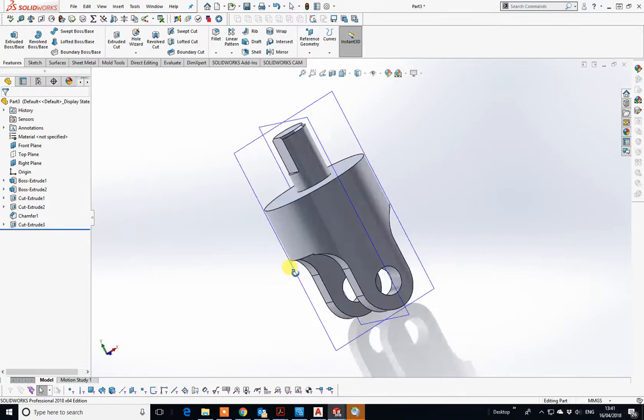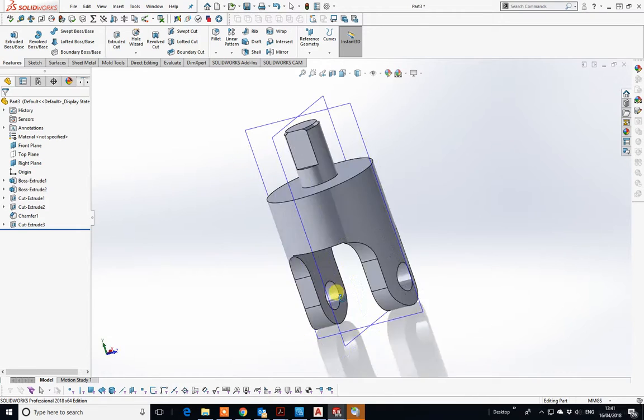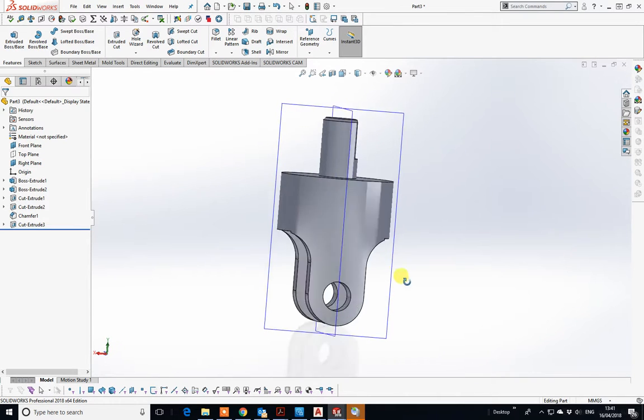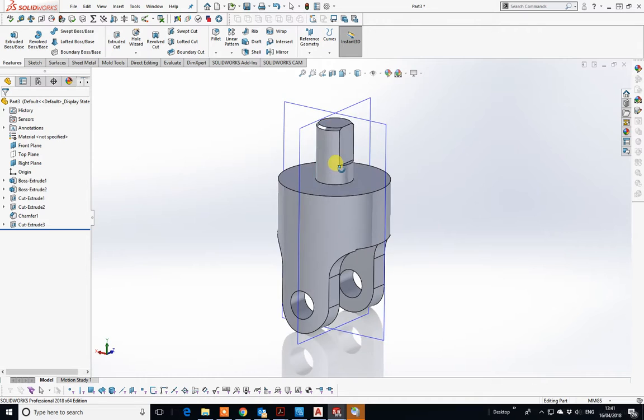Okay, this is the male configuration of the yoke, and we now need to do the female. But you'll notice from the drawings the only difference I've spoken about before is that this male part is different to the female part. The female part as a whole has a spike that comes out the top. Now we can do this by using what they call a configuration.